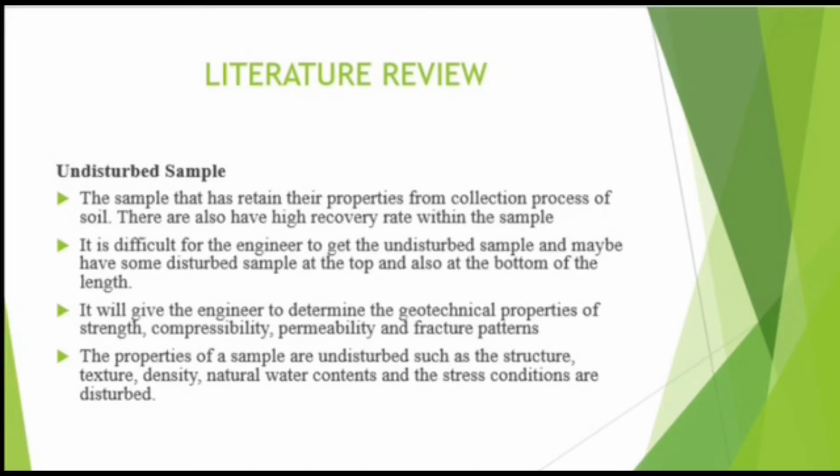An undisturbed sample is a sample that has retained its properties from the collection process of the soil. It also has a high recovery rate within the sample, and it is difficult for the engineer to get a fully undisturbed sample, and there may be some disturbed sample at the top and also at the bottom of the line.